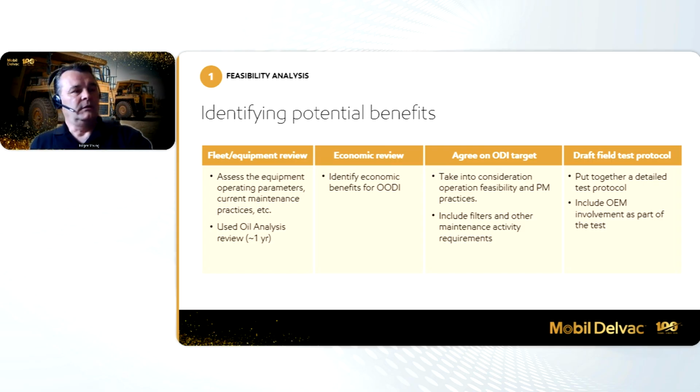This takes a little look into the past. What has been happening before? Why were we changing oil here? What was the PM schedule like at this time? And sometimes we can pick out trends that can be very useful to show, maybe we have some seasonal things going on with your historic used oil analysis that we can address now moving forward.